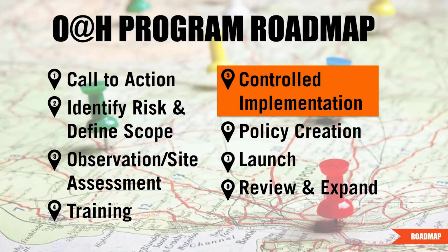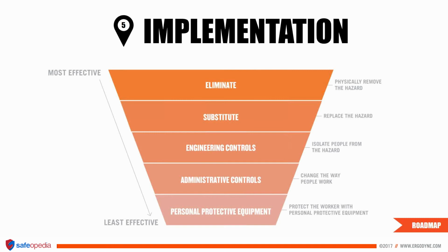This is going to be implementing a program within that pilot area. So you're going to go through, revisit your hazard evaluation and your pre-task planning, and you're going to go through those areas that you marked in red, for example, that have high risk for dropped objects, and you're going to walk down this hierarchy of controls and determine, hey, can I just eliminate this outright?